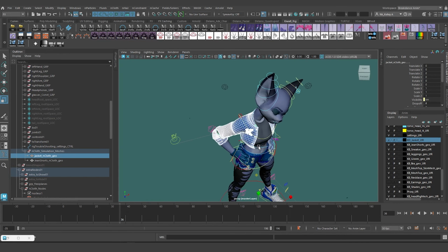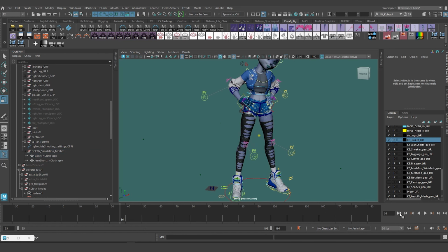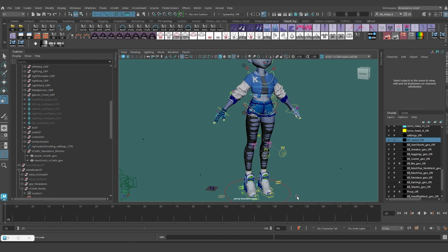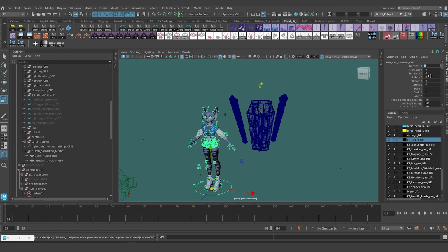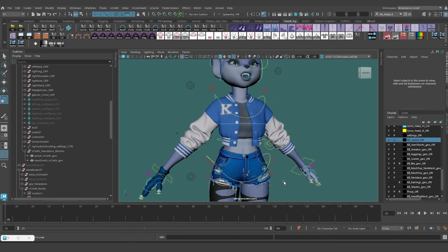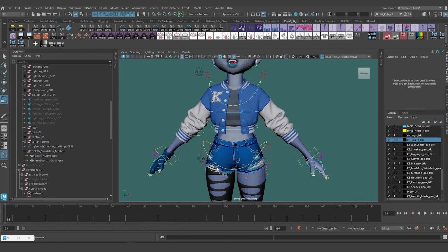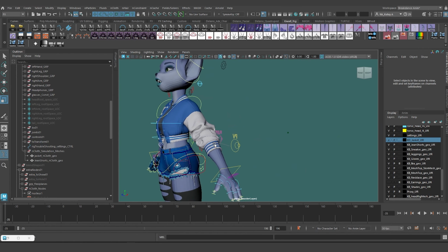You can scale the rig, move the rig, and everything is going to work. Now I'm going to go back to 0 and reposition my rig. And if I hit play, the point to surface constraint should jump back into position. So I think that's it for the cleanup. Now this system is ready to be used, and I can move on to the next part of this lesson.